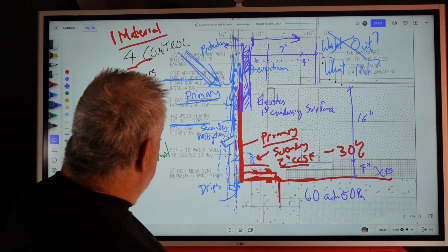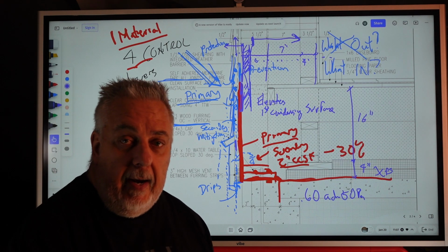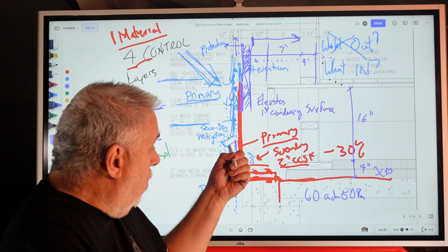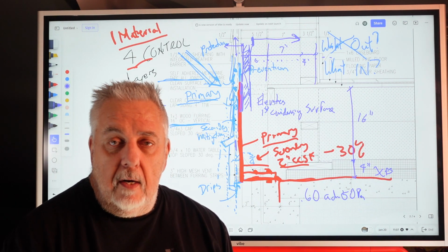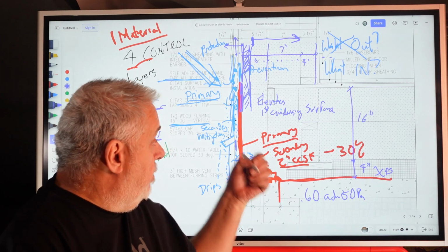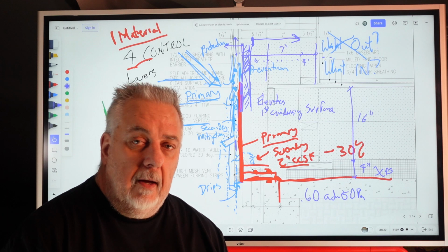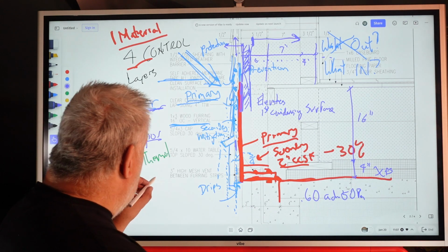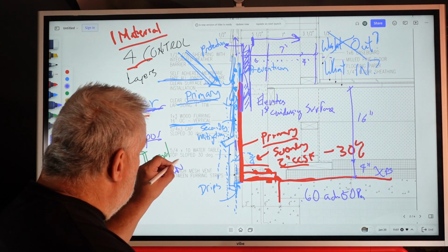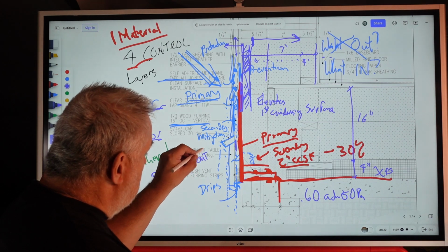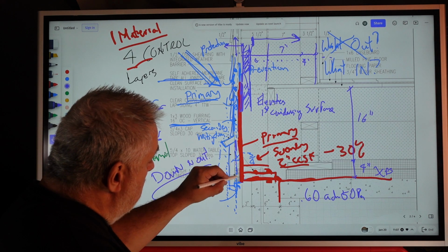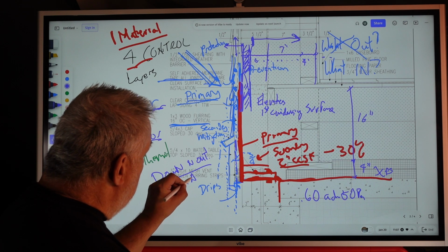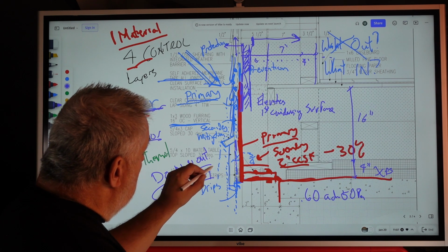While we talked about using it as drainage for water, it is also a ventilation path to whisk away and dry out the moisture content of our exterior sheathing or the backside of our wood siding, whatever the case may be. It provides not only what we would call down and out, that's our term that we use for water, but it also provides up, in, away, right?